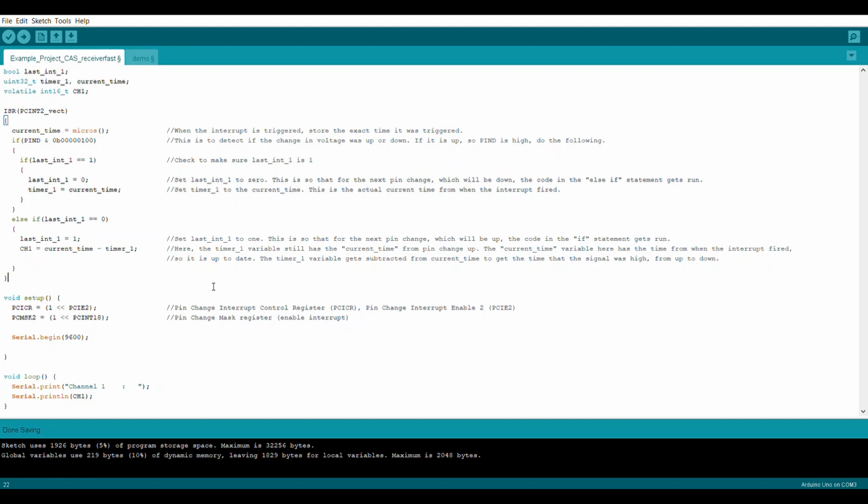It emits a pulse 250 times per second, and the pulse is between 1000 and 2000 microseconds. And of course, if it's 1000, it's like 0% control stick, and if it's 2000, it's 100% control stick.